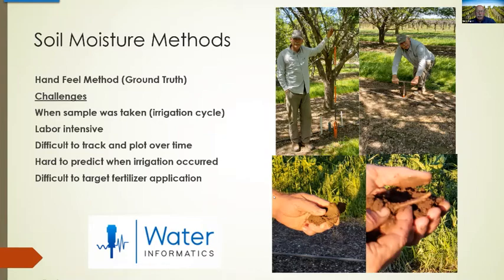You can see that we're about 3 foot off that tree, probably 3 foot to the south of it, and we try to put those sensors just about in the drip line. The reason those 2 steel stakes are there is because when we run our sweepers through, we just want to make sure that they don't get damaged. But this is old school in how you do soil moisture.